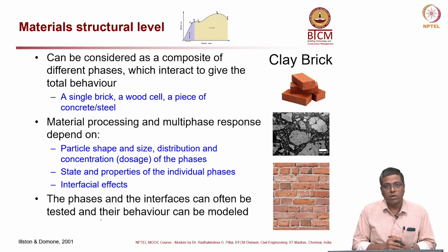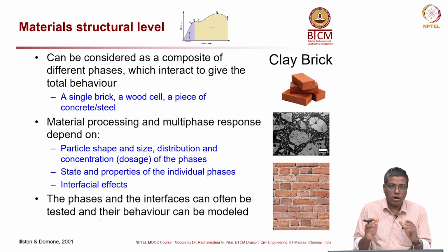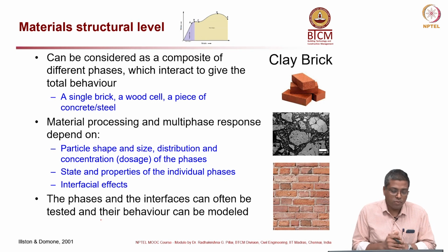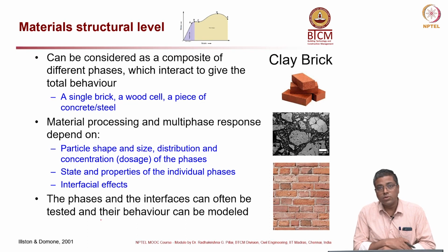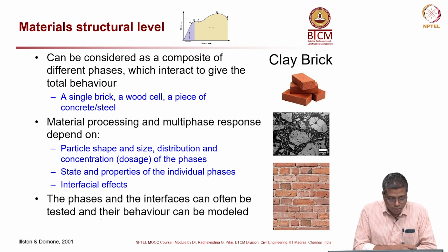And in the third picture, at the bottom right corner, you can see the interface. When you talk about a clay brick wall, you also have to worry about how the mortar in between each brick is bonding the clay bricks together as a single wall unit. So all these interfaces, and how the properties at the interfaces are, are very, very important, in addition to the interface between the various particles within the clay. Now, the phases and interfaces can often be tested, and their behavior can also be modeled.